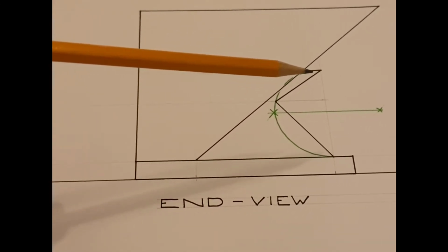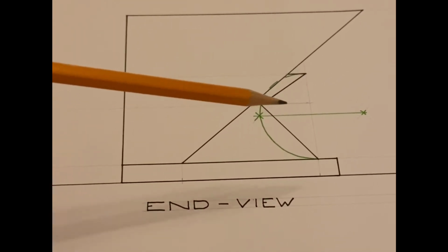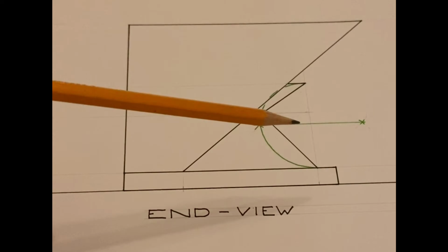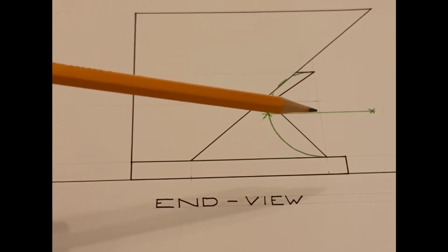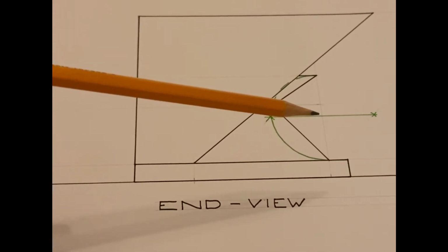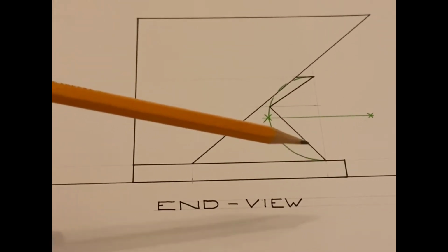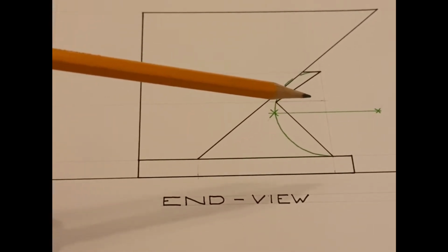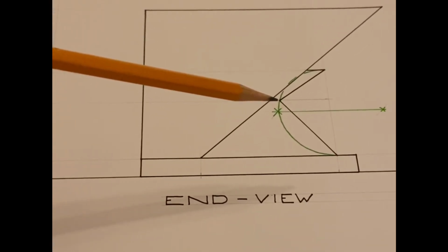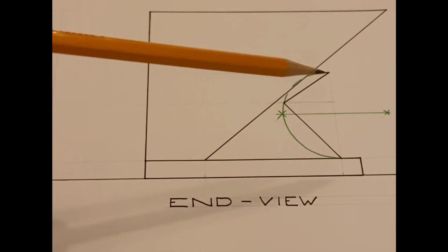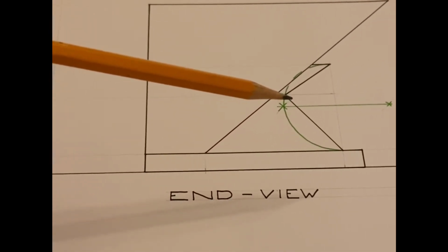The distance from here to here is 55. So you take your compass and you bisect this line. Where the bisector cuts the 55 millimeter line, that will give you the center point for the circle. You put the point of your compass there and draw the semicircle. Then you measure up 35 millimeters and draw this line. Where that line cuts the circle gives you the point you're looking for. Join from here up to that point and back down, and you have a 90-degree angle here at the circle.